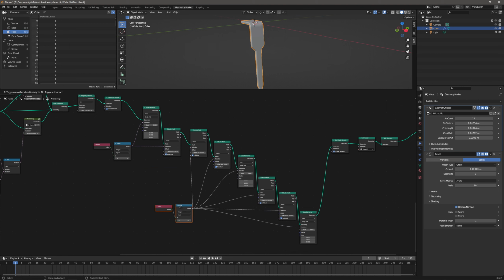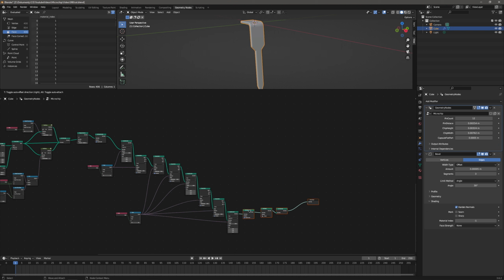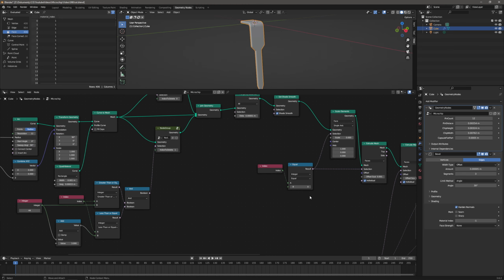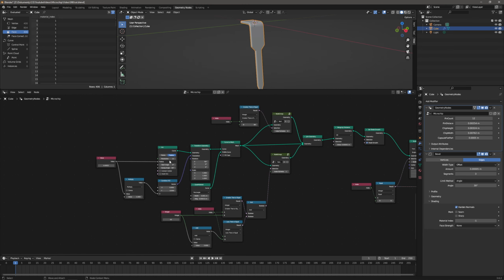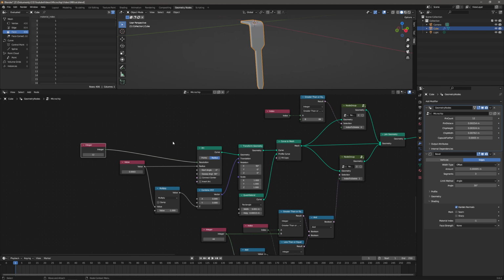Well, I told you that I will tell you about the mathematical way to determine the indices. Well, I experimented with it. It all depends actually on the resolution of the initial arc that you make, because when you decrease it, for example, to 8, we will get all screwed up. So now we're back with the resolution 12. Let's actually input it as a variable, as an integer value, and we will depend on that.